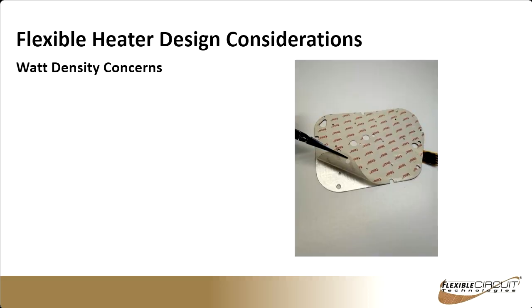One thing that we do, if you have a low thermal conductivity heatsink and we want to try to drive it a little bit harder than we normally would, is put a foil backing on the heater. This is a fairly inexpensive way of giving you a little bit more power rating on your heater, even though your heatsink isn't going to be able to pull the heat away as quickly.